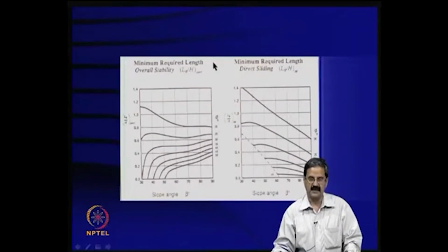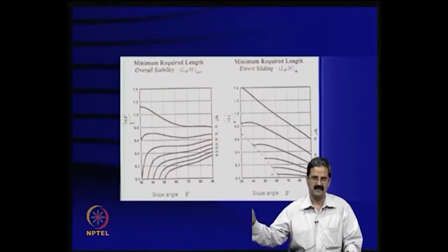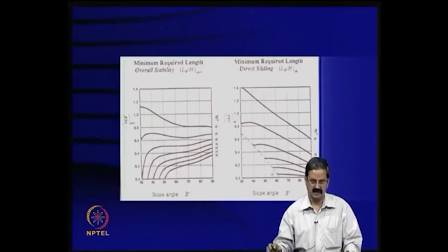And as I just mentioned, we try to calculate the required force, and also what is the length now. It is very important to understand that, as I mentioned in the previous class, if the height is say 10 meters, 0.7 times will be the length of the reinforcement.